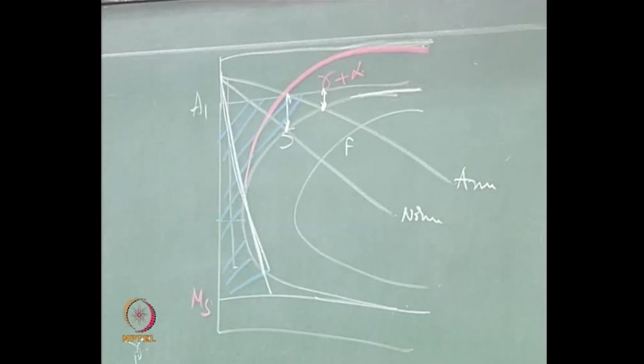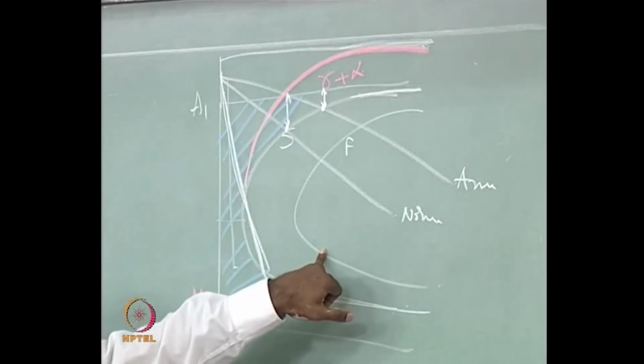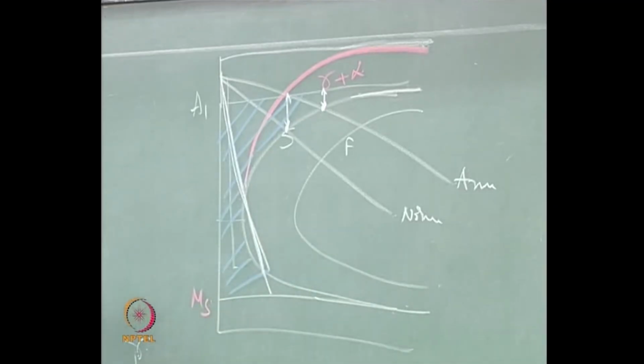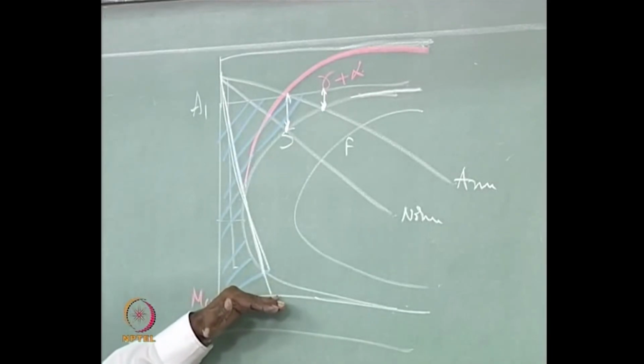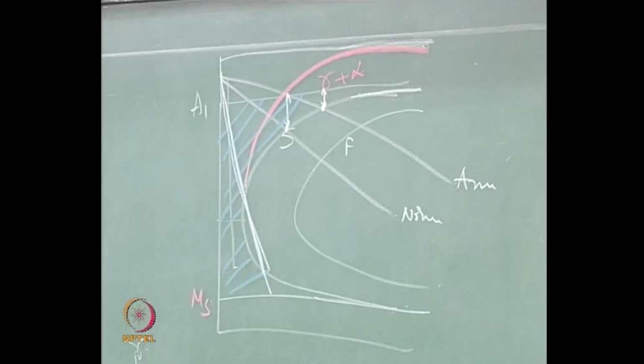It will straight away give you some pearlite, but because the cooling curve is not intersecting this, only some amount of gamma will transform to pearlite, the remaining gamma will be left out, and once you reach below the Ms, that remaining gamma will undergo a martensitic transformation. So such an alloy would not give you any proeutectoid alpha, it would simply give you pearlite plus martensite.